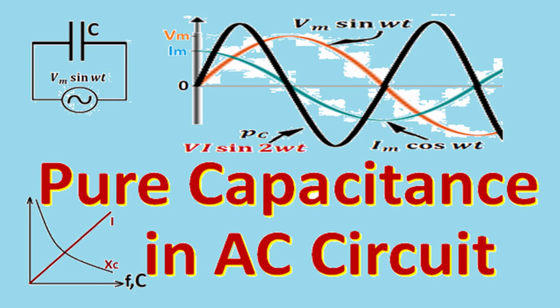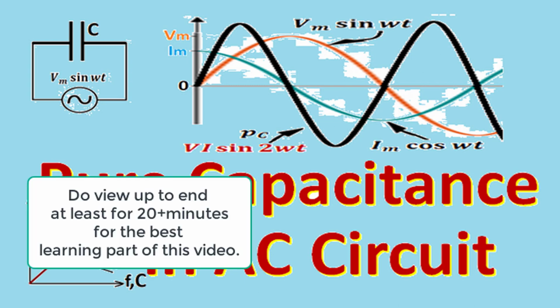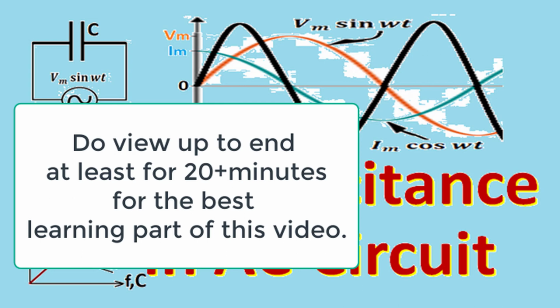Today in our playlist Basic Electrical Engineering and Class 12th Physics, in our chapter Alternating Current Circuit, we'll understand the behavior of pure capacitance in alternating current supplies, and will understand that when a sinusoidal alternating voltage is applied across a capacitor, the current through the capacitor is again a sinusoidal current of the same frequency, but current leads voltage by a phase angle of 90 degree.